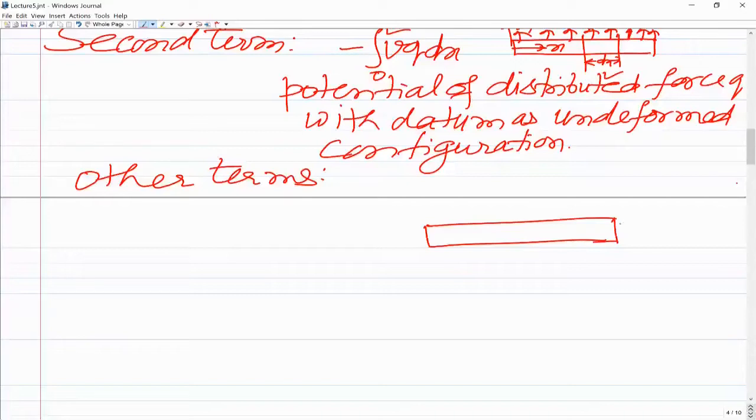On the right side we have the shear force, which is capital VL, and because the coordinate system is x y, the shear force is along the positive y direction here, and this is the bending moment ML. On this side the shear force is V naught, and the bending moment is about the negative z axis, so that is M naught. So these are the forces in the beam. Depending on the boundary condition, some of these would be 0 and some non-zero, depending on how the beam